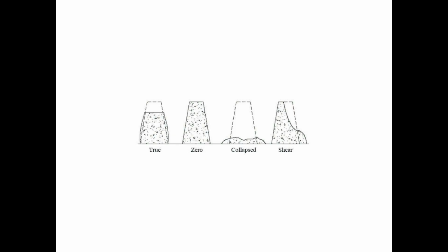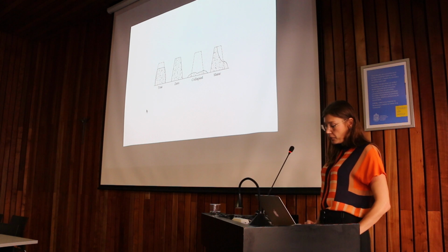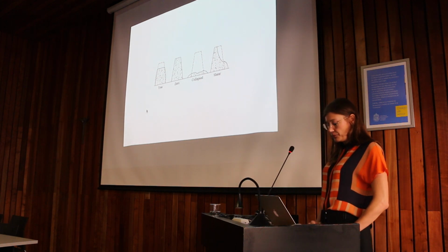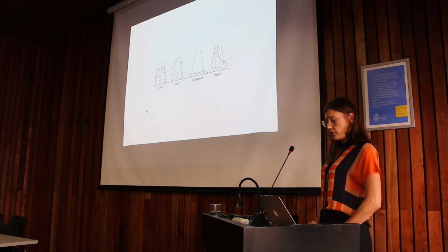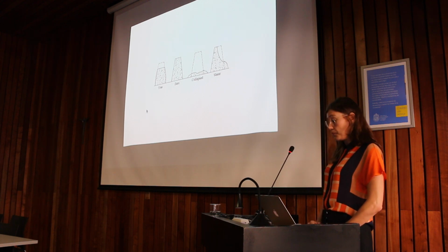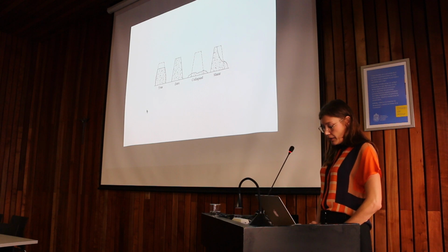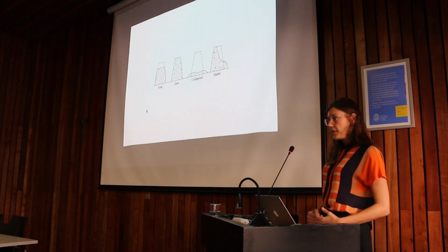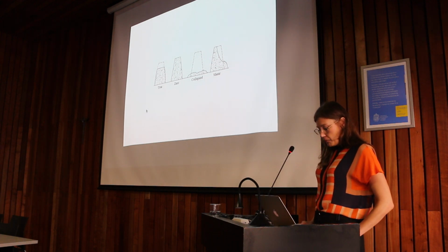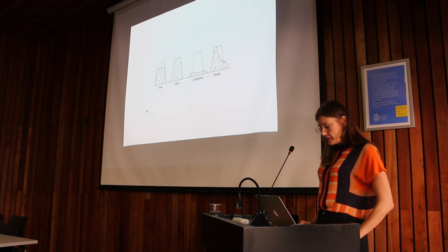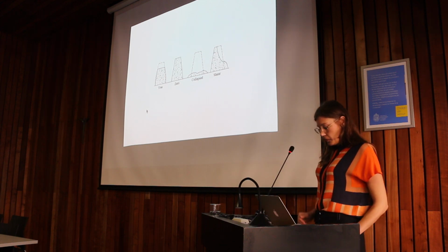Whether cast in situ or prefabricated, the process of casting inevitably adheres to a sequence of operations in which fresh concrete is displaced inside a pre-prepared mold. Concrete owes its fluidity to the presence of water, but unlike water, it has a certain resistance to deformation, which means that it doesn't necessarily self-level when poured into the mold. It slumps. Concrete's success as a casting material lies in overcoming this resistance to deformation by vibration or by chemical additives so that it flows into every corner of the mold.